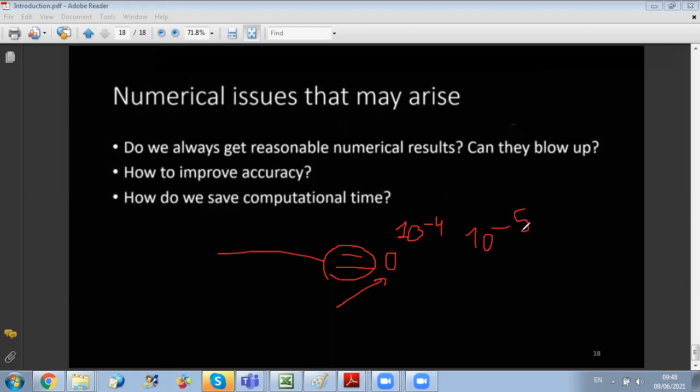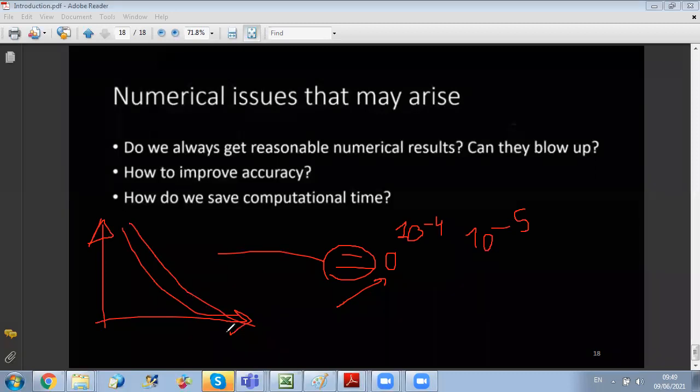And I will consider that my CFD model has performed the required calculation, and I can take the temperature and velocity. So you will observe your residuals during a CFD simulation, and how they are decreasing. This is what you wish: that the residuals decrease until reaching a certain criterion that you specified, for example here 10 minus 5. Automatically, when it reaches 10 minus 5, it will stop, because you set the convergence criterion to be residuals equal to 10 minus 5.